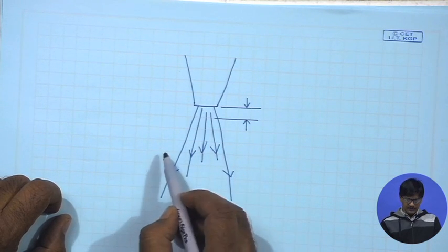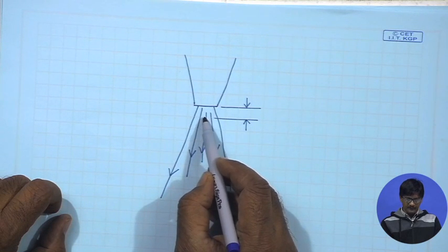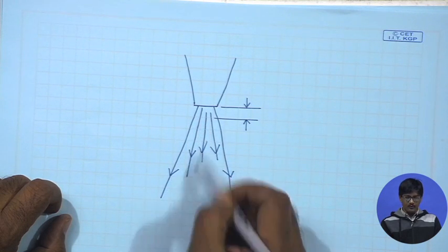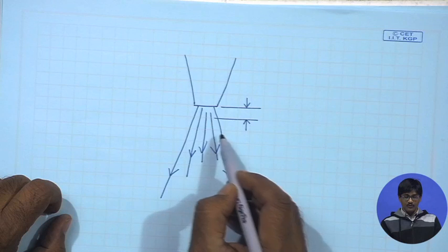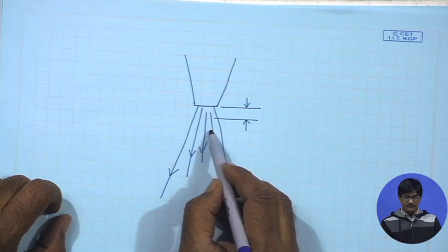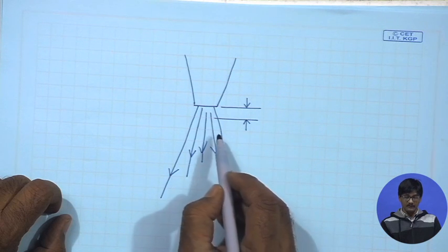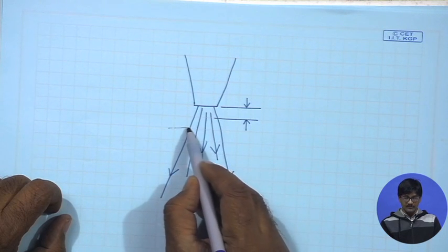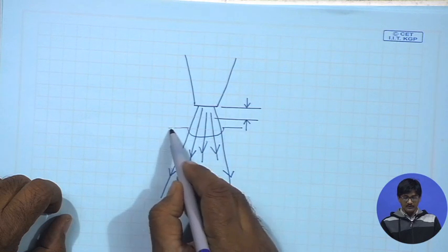So, first of all, if you are interested in cutting very precise, thin, narrow lines, okay, if you want to make grooves of very narrow curve fit, if you go on moving away from the nozzle tip, that means if the standoff distance becomes higher and higher, first of all this is going to give you a wide cut which might not be your requirement at all.